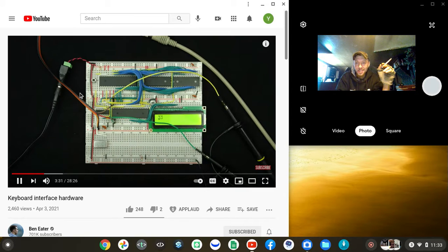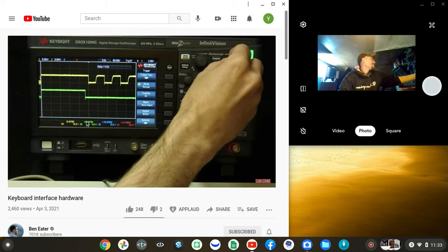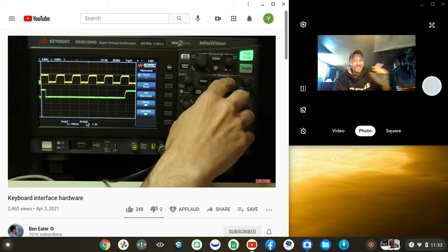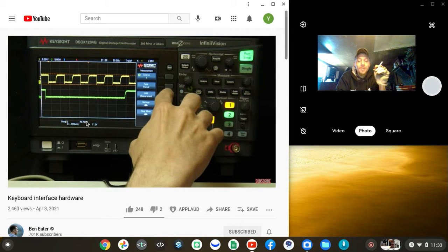I/O port here, and just read one bit at a time for every interrupt, and from that piece together the entire message from the keyboard. We could do that, but I don't think that's ideal. And the reason for that is, if we look at the timing of these clock pulses, you can see that if we try to measure the period.